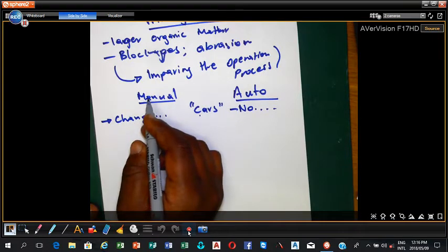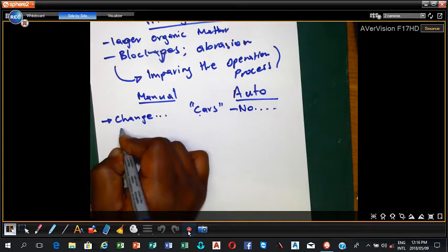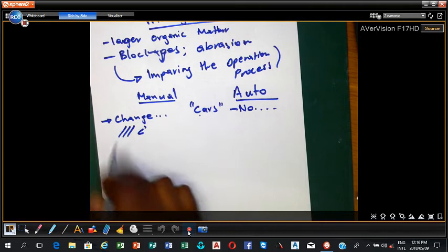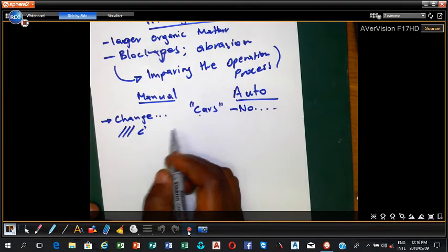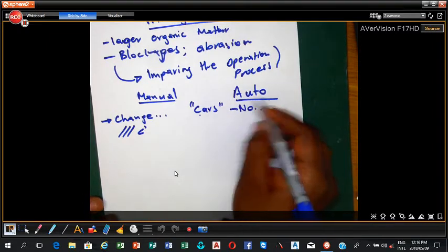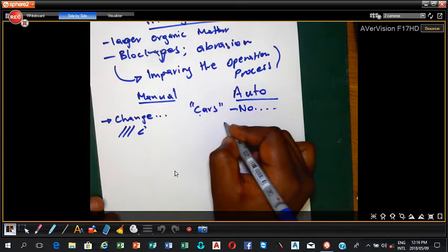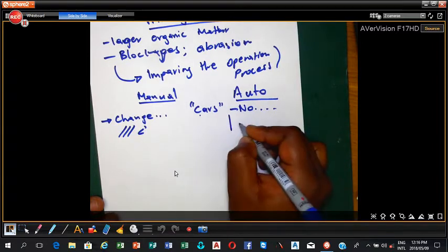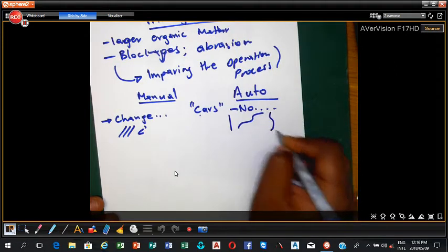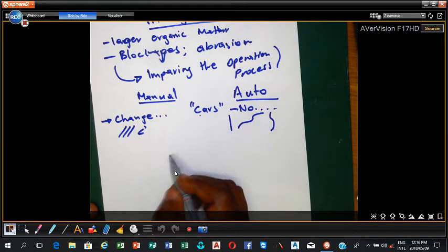But if you look into the essence of the screenings, one, the screen itself, the bus screen, needs to be at an angle. That's what is important for cleaning purposes and so forth. But also, if you are looking at the automatic screens, it doesn't matter if it is vertically straight, at an angle, or skew, because there is no one who's going to rake. It's only the machine that rakes itself.